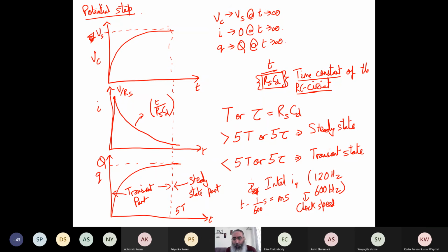When you want to measure picoamperes or femtoamperes of current, femtovolts of voltage, or very low femtocoulombs of charge, you have to shield even the current carrying lines which connect the different components and do the measurement for you. Even those have to be shielded from the external electromagnetic sources. That is done by what are called coaxial and triaxial cables.